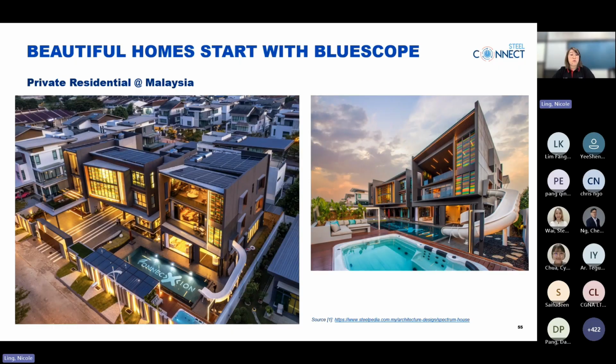Steel roof can work very well with solar panels. A flat roof can maximize PV capacity and efficiency, is easier for integration, and allows greater energy generation. Over the life cycle of the building, maintenance access is essential. Technicians will still need to walk on the roof for PV inspections, cleaning, and also servicing. Steel roofing provides a stronger, safer surface for maintenance traffic, reducing risk and damage compared to fragile tile roofing, which is prone to cracking, displacement, and breakage under foot traffic.